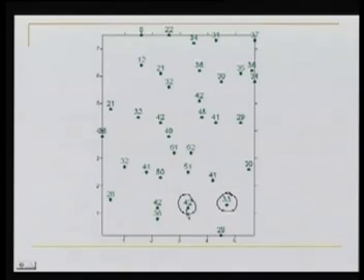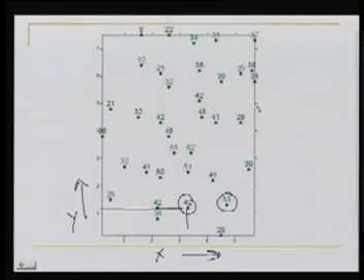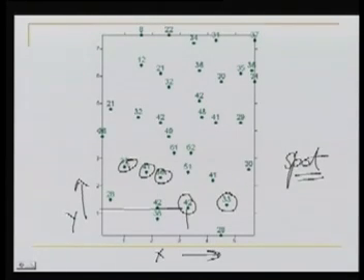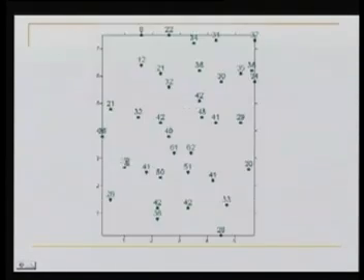We know their location in x and y. So this is x and this is y. It's a map of spot elevations. These are the spot elevations. For each point, I know its RL. Now, for all these points, we want to generate a contour.